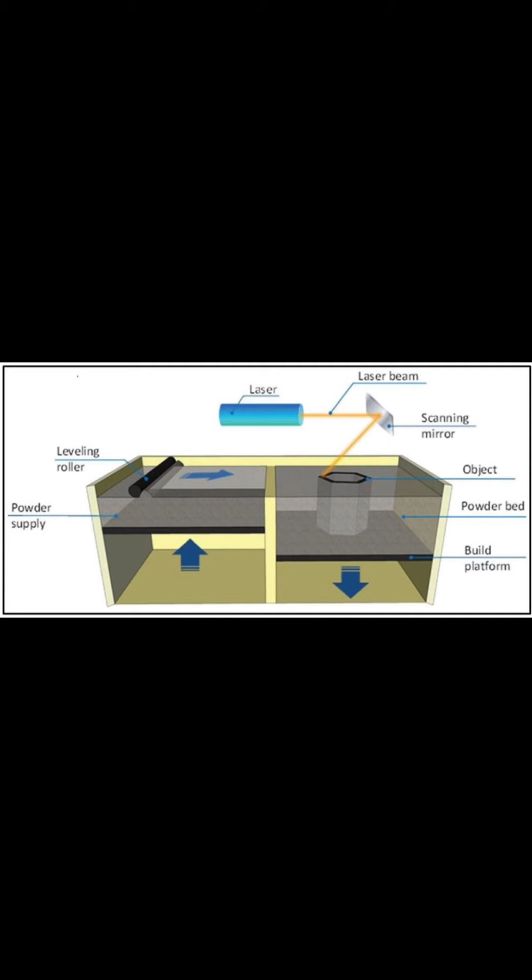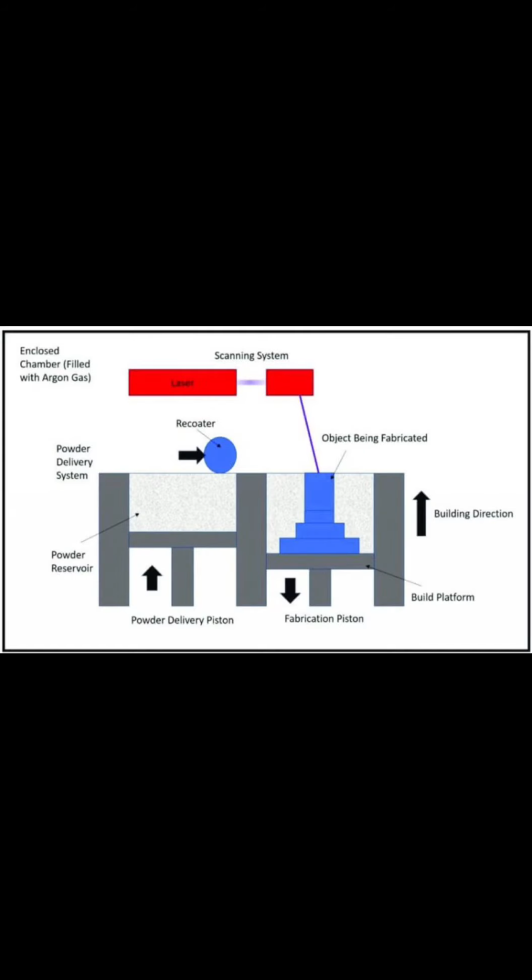With selective laser melting, thin layers of atomized fine metal powder are evenly distributed using a coating mechanism onto a substrate plate, usually metal, that is fastened to an indexing table that moves in the vertical axis. This takes place inside a chamber containing a tightly controlled atmosphere of inert gas, either argon or nitrogen, at oxygen levels below 500 parts per million.